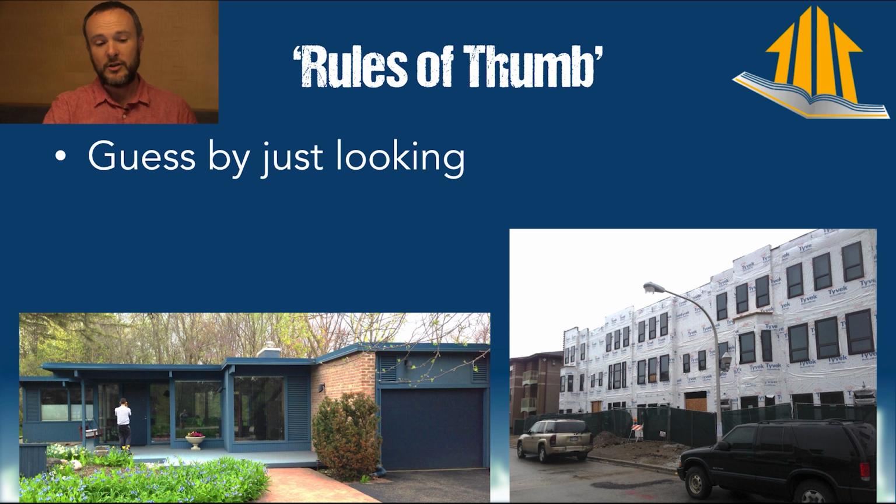What people used to do is just look at a house or ask you how many square feet your house is, and they'd say, okay, that sounds like a 2-ton or a 5-ton air conditioner. When I was first starting out, I had a mechanical engineering firm, very well respected, tell my client who was building an 800 square foot high performance, very well insulated condo that they needed a 5-ton air conditioner. That was the beginning of my journey into telling mechanical engineering firms how this works, because a lot of them are using a commercial software which has nothing to do with residential.